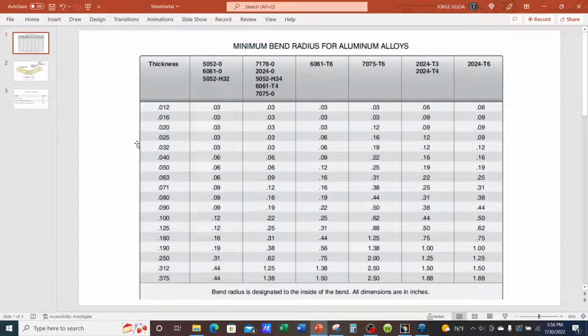Alright, so K factor. What's a K factor? So first you would pick your material. Typically at work, we work with aluminum 6061 T6, 7075 T6, 7075 O temper. The temper tells you how this material, in this case an aluminum alloy, was treated. Was it heat treated? Was it annealed to give it strength, to improve on the properties of the material, for example?